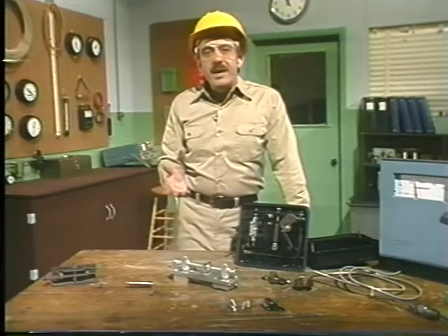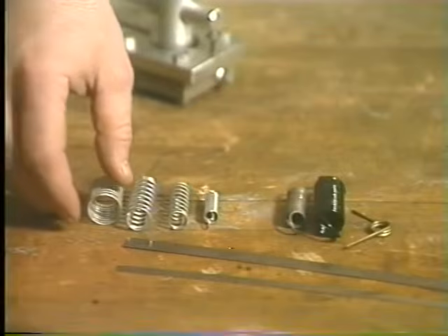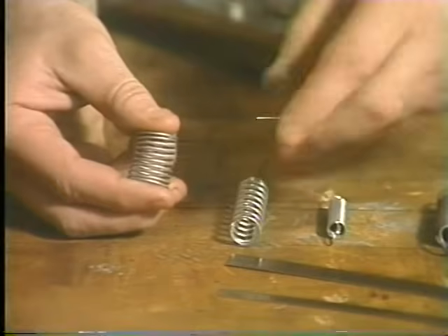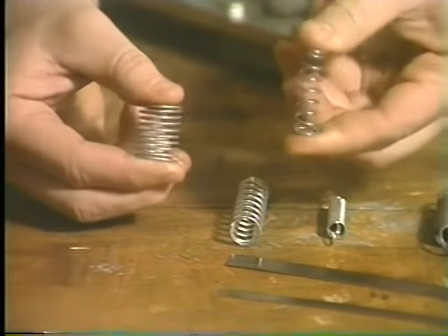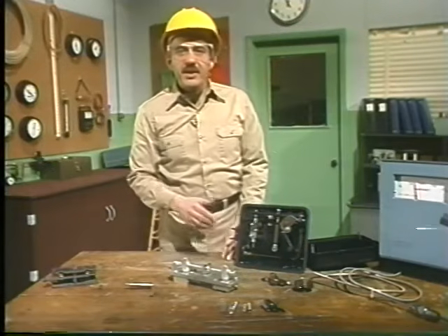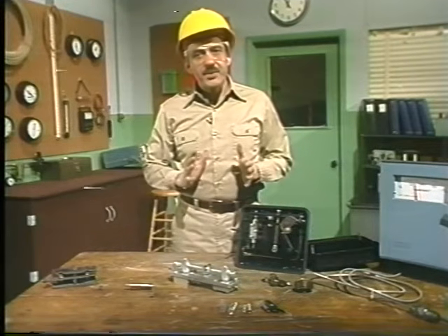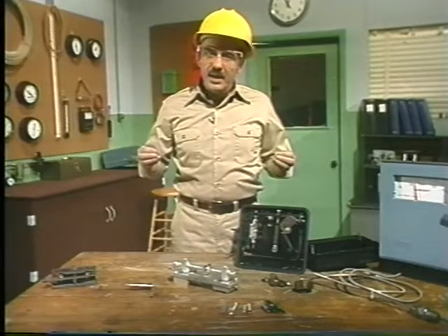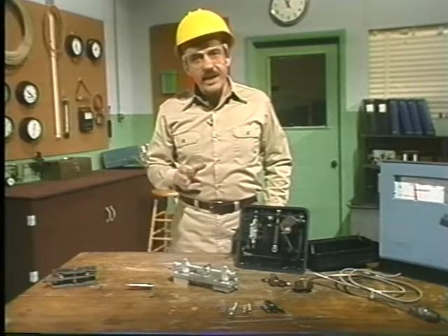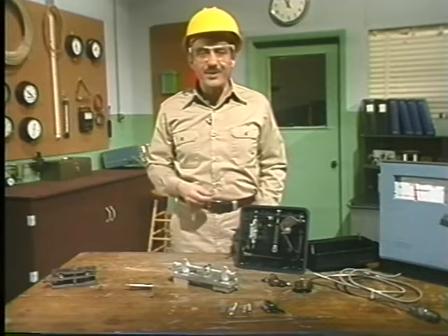Now, these rules of thumb about length and thickness in straight springs also apply to coiled springs. In addition, coiled springs with large diameters are more flexible than coiled springs of the same material with smaller diameters. Now, generally, coiled springs can be divided into two categories: those that are specifically designed to resist compression and those that are designed to resist extension. Both kinds of coiled springs have the same purpose that all other springs have, and that is to deflect a precise distance for a known applied force. They're just designed to move in different directions.